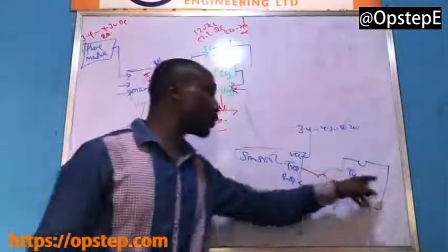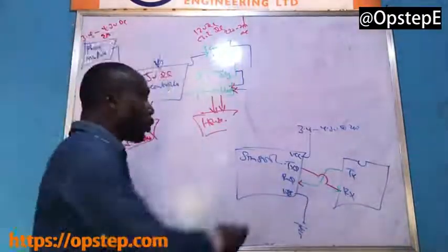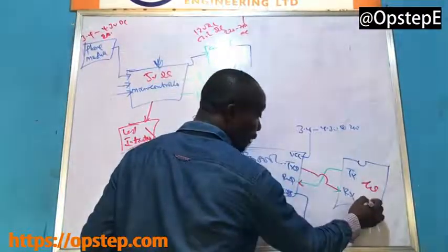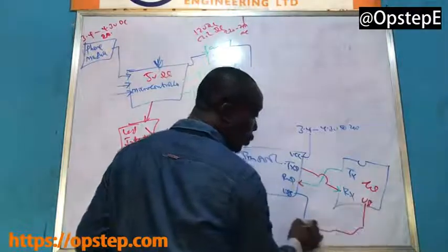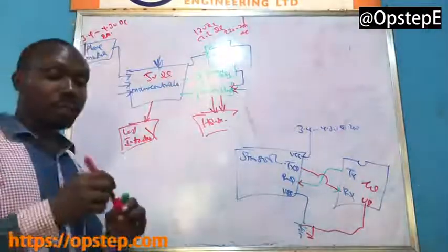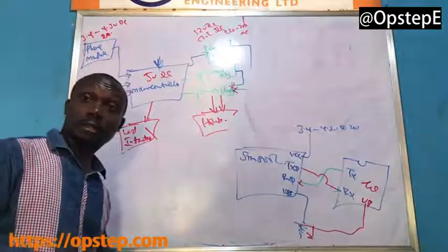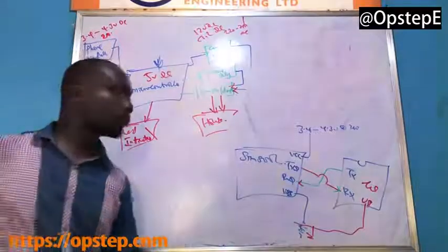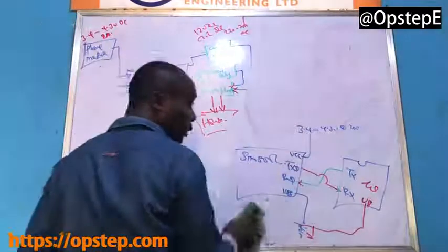So this is how they are connected. But understand that this is your microcontroller, and it also has a VSS pin, which must also be connected to the negative of the supply for the transmission to be complete. Does it make sense? Alright. So that's how it's connected.